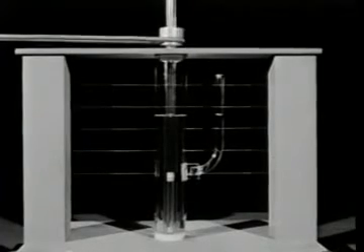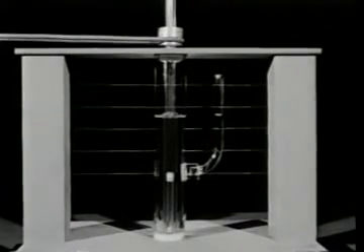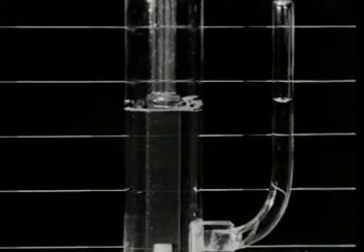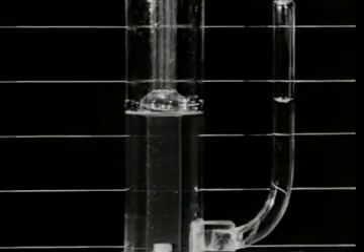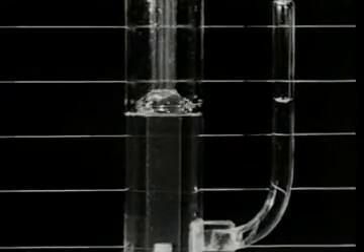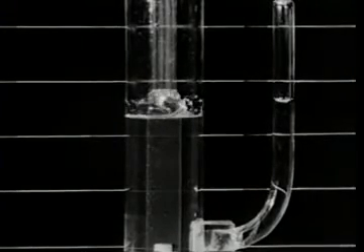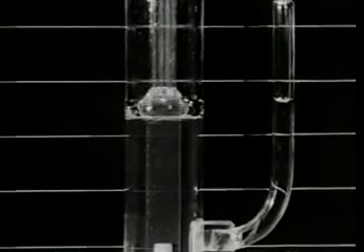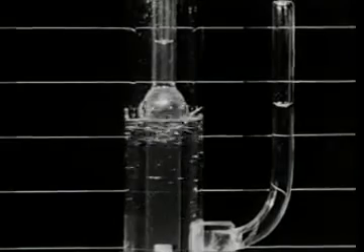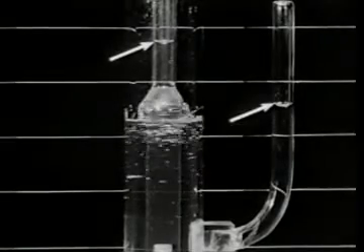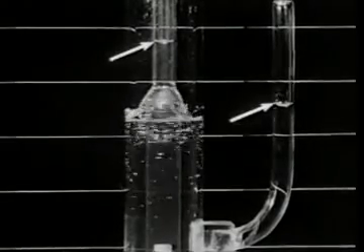When the central shaft is rotated, a shear flow is established in the annulus. The polymer solution climbs up around the rotating center tube as the cake batter did. Because the fluid is so viscous, it took about an hour for the level of the fluid inside the tubes to indicate the steady-state stress difference.